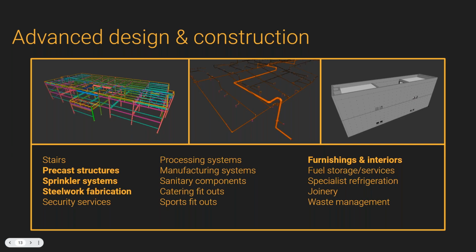We've got a fabricator model on the left. Those can be challenging to coordinate, depending on the software they originate from. We have sprinkler models. Again, they need particular attention, especially in making sure that they don't intersect with existing services. And then we have a precast model there on the right. The challenge with precast models is ensuring that the formed penetrations match the services. That's a separate rule set that we have to make, but it's definitely worth doing, because manual coordination of that is quite difficult. It's quite an involved task.